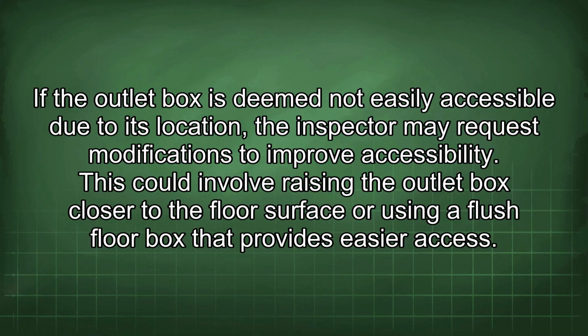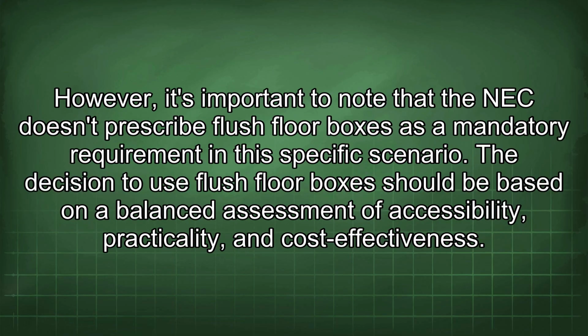This could involve raising the outlet box closer to the floor surface or using a flush floor box that provides easier access. However, it's important to note that the NEC doesn't prescribe flush floor boxes as a mandatory requirement in this specific scenario. The decision to use flush floor boxes should be based on a balanced assessment of accessibility, practicality, and cost-effectiveness.